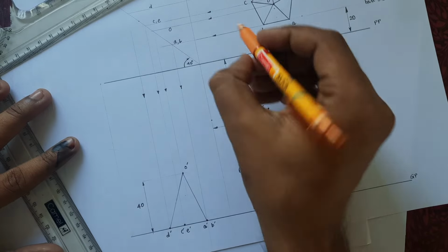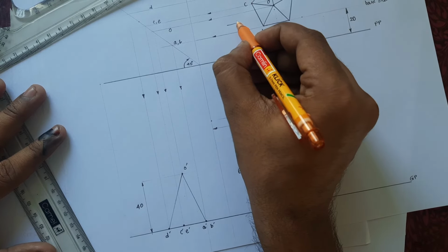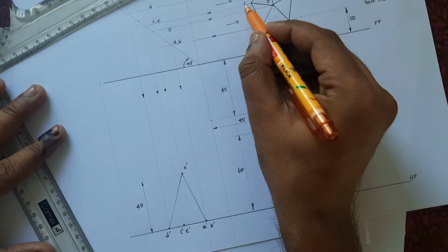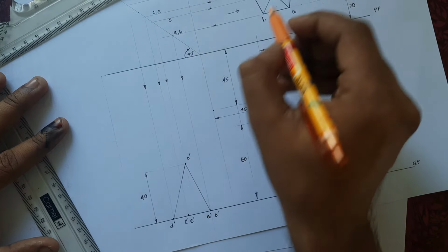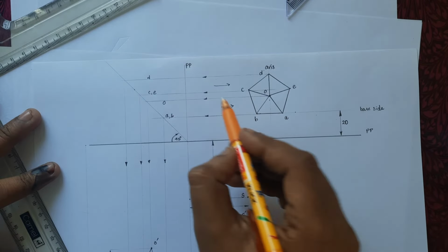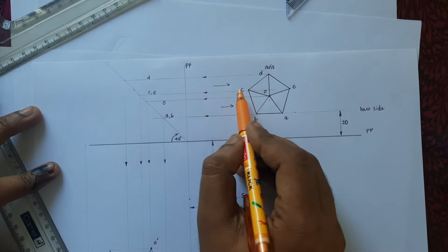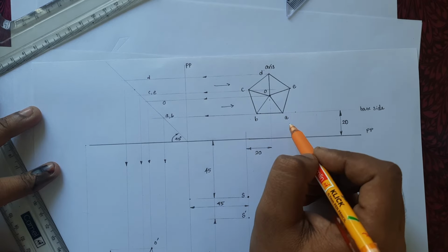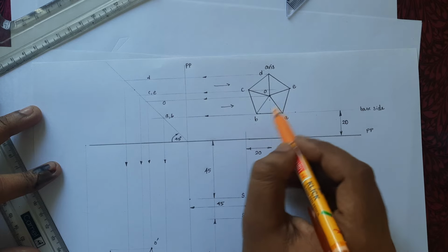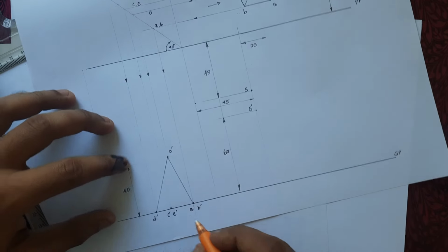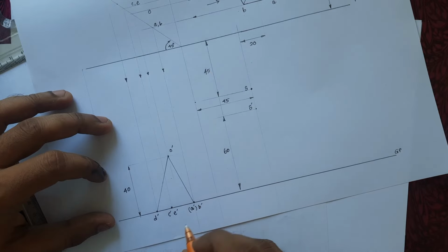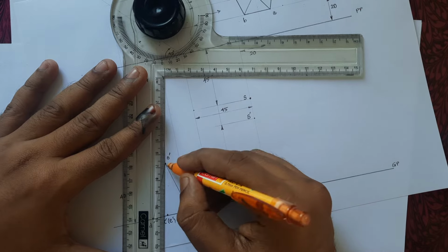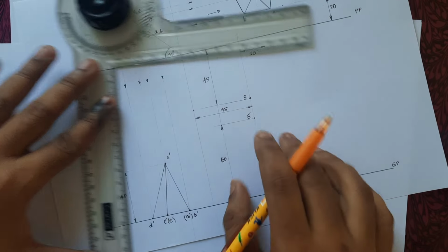And then we have drawn the left side view. From the left side, we can see B, C, D. So B, C, D are visible. E and A, sorry. All we are doing is the left side view. From the left side view, we can see D, C, B, and A, E are invisible. A is hidden by B, E is hidden by C. So we have to mark the hidden points like that. So clear?